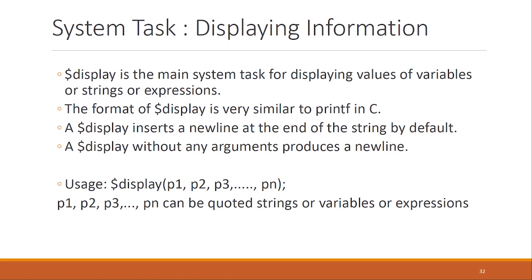And the system task that you need to display some information to the user is $display. So think of a scenario like this. Now you have modeled the circuit in Verilog, and now you need to give certain inputs to the circuit, and you want to see whether the circuit is working properly. So how you can do this is by getting the output of the circuit displayed on monitor. So to do that, you can use this display system task.